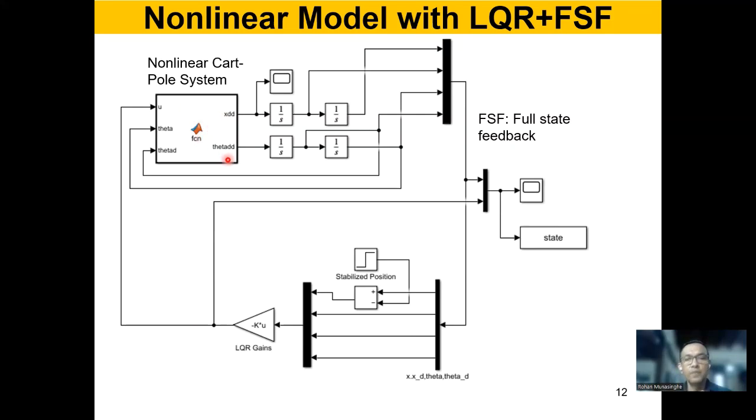This one, okay. So the Simulink function runs the nonlinear equations x double dot and theta double dot. You can see the two things over here, x double dot, theta double dot, but it needs control signal u, theta and theta dot. And I think x dot is also required. I have to modify this one. X dot is over here. This is x double dot, this is x dot. There should be a link over here, from here to here. I'll check that out.